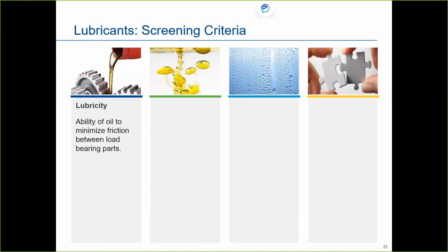Lubricity is very, very important for everything we do with compressors and our components. Okay, we have to get that oil around. We want our refrigerant lines to have at least a ½ inch fall in every 10 linear feet. We need to trap properly. Okay, we have to have everything going for it.